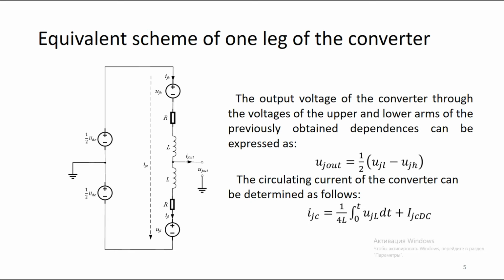As such modules, the bridge variant allows us to obtain a bipolar output voltage, which is used both in terms of increasing the flexibility of voltage balancing on capacitors, and in terms of the possibility of reducing the magnitude of the emergency current. The use of circuits with a fixed zero point and with flying capacitors allows us to significantly expand the number of switching states and therefore requires more complex control methods with the ability to maintain voltage balance on capacitors.